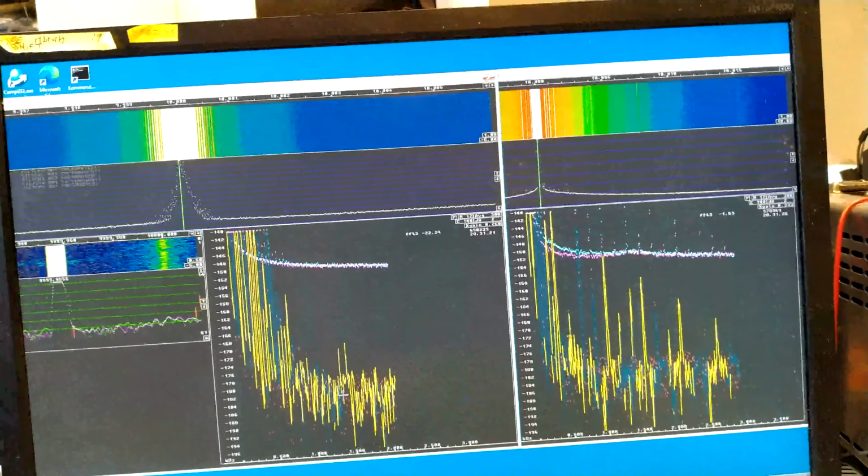The uncorrelated spectrum is at minus 150, while it is at minus 154 with the SDR IP. So after 1 hour, that's 10 times more, I should see about 4 or 5 decibels lower if I don't have any artifacts in the systems.